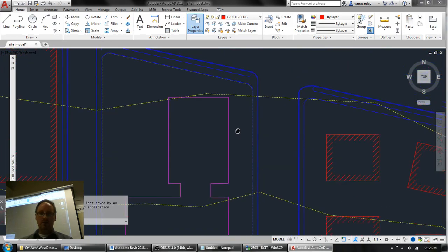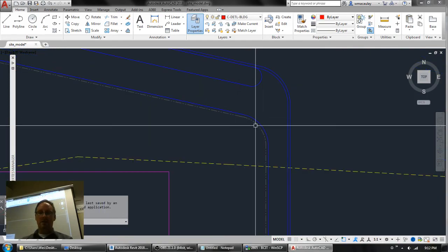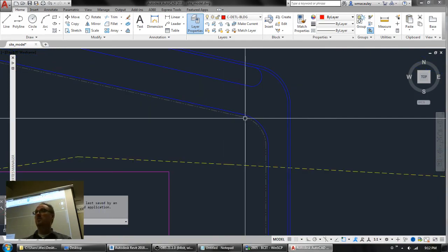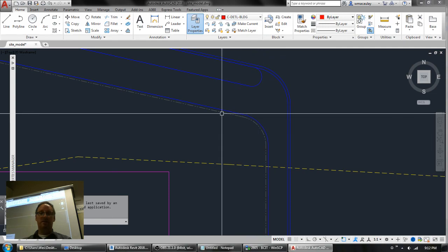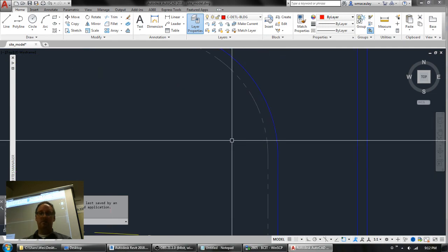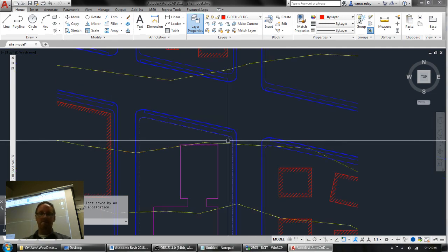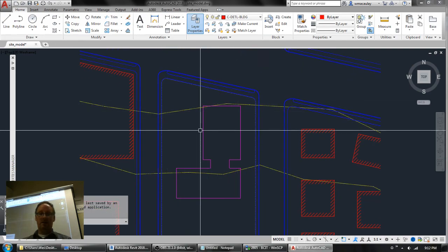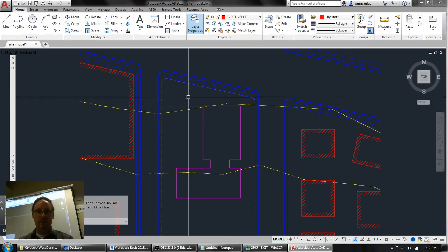So you're going to need to use the split surface command. You're going to need to put in the property lines using the property line tool, and you'll just be able to pick that gray line, which is the property right there on the screen. And of course, this has got polylines that have Z coordinates.